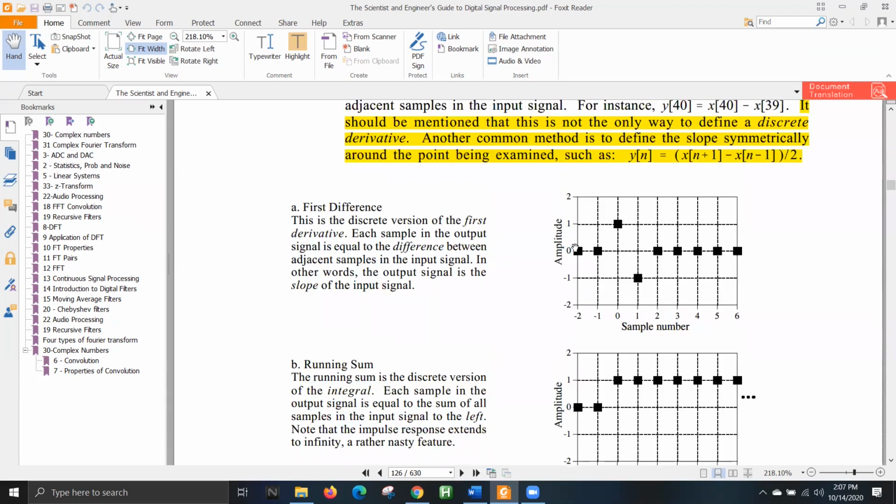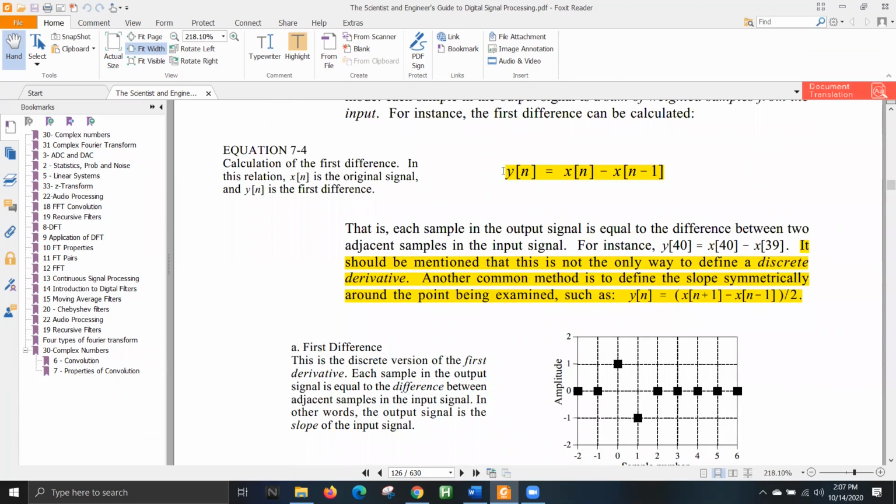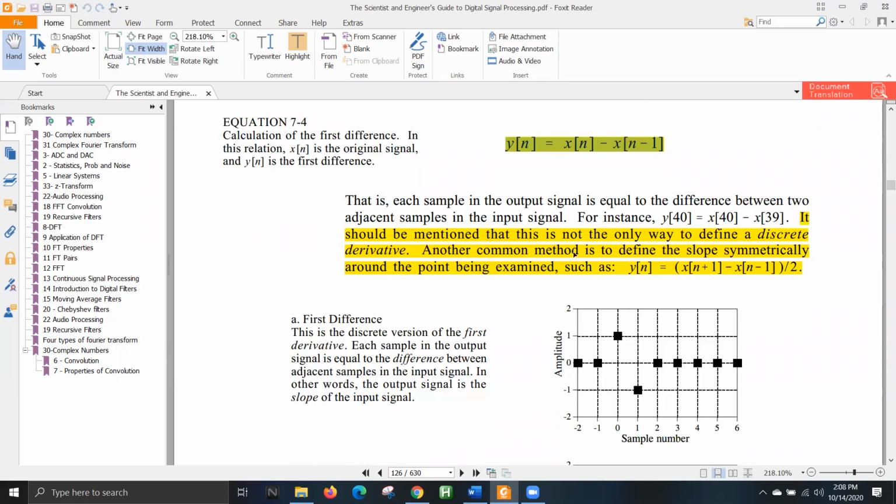Okay, and in that case, what will the graphical representation of this system look like? What this system is basically doing is convolving, and how you will get this behavior for each of the output points is: if your h[n] is something like this, a delta function and also a shifted and inverted delta function, then this is what will happen when you convolve this signal with x[n].